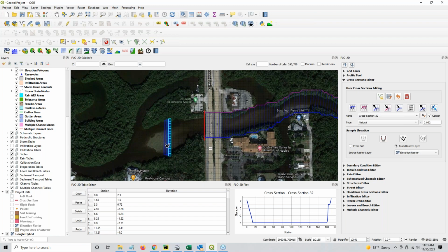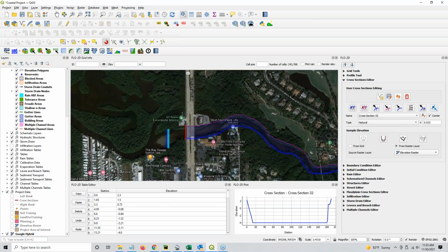The same thing is going to happen with the tide control. At the beginning of the simulation, before the rainfall starts, the tide is going to come up, go into the channel and start to fill the channel from the downstream side. It's an actual time-related control right there. So you don't have to do anything in this particular channel. You just need to make sure that you set it up so that it's terminating correctly, or you can bring it all the way down and set the tide control to the channel instead of to the floodplain. You can do it both ways.